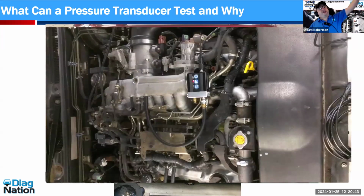And gosh, how could we talk pressure transducer and not throw in the basic one that many of us started with all the way back in the early days of the Allen scope and the Sun scopes and all of that: intake manifold pressure. But in this case, with our lab scopes and a high quality transducer, and more than the transducer, because by the way, it can be delta or absolute. I'm showing you absolute in this picture, but with good quality software to run with your lab scope, we can tell an immense amount about the mechanical integrity of the engine by monitoring not just overall engine vacuum, but how each one of the individual cylinders breathes from a volumetric efficiency standpoint. So, once again, incredible test with a lot more detail to be seen later.